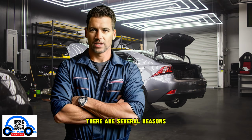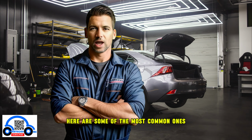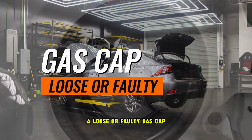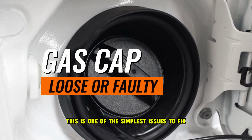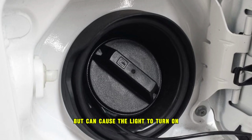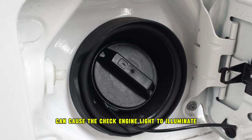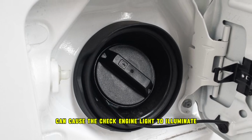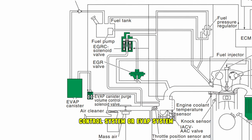There are several reasons why the check engine light might come on. Here are some of the most common ones. A loose or faulty gas cap. This is one of the simplest issues to fix but can cause the light to turn on. A loose fuel cap can cause the check engine light to illuminate, due to its impact on the vehicle's evaporative emission control system, or EVAP system.